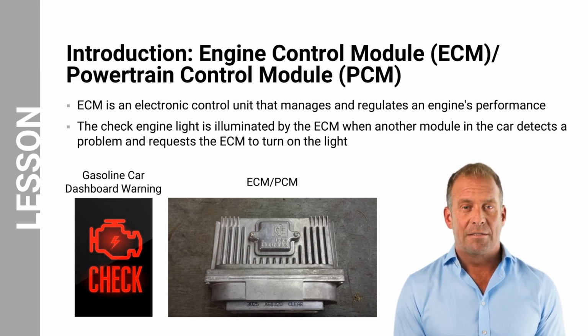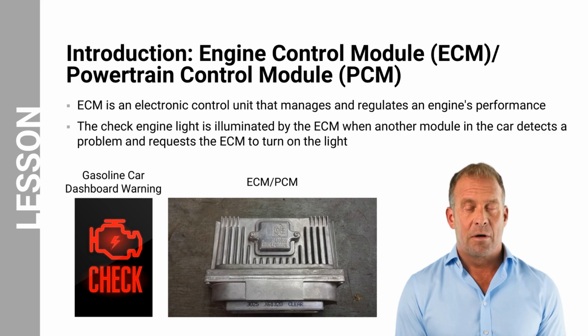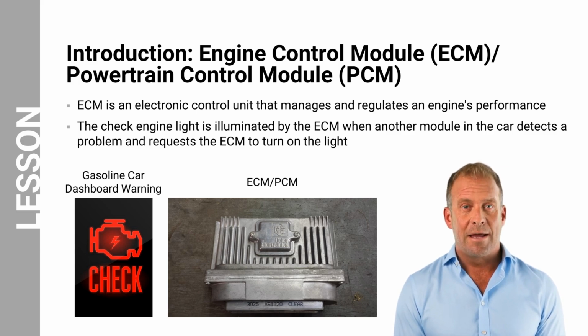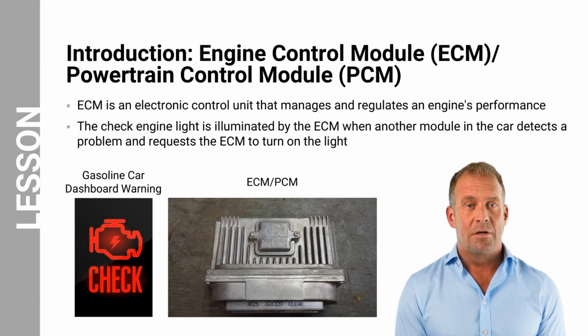The ECM acts as the control center for gasoline or conventional cars that have internal combustion engines, abbreviated as ICE, monitoring various sensors and modules throughout the car. When any of these components detect a fault, they communicate with the ECM, which then triggers the illumination of the check engine light. A BEV has electronic systems controls, but no ECM since there's no combustion engine.